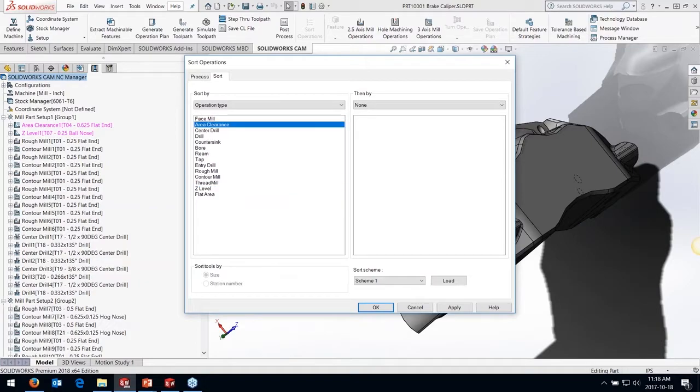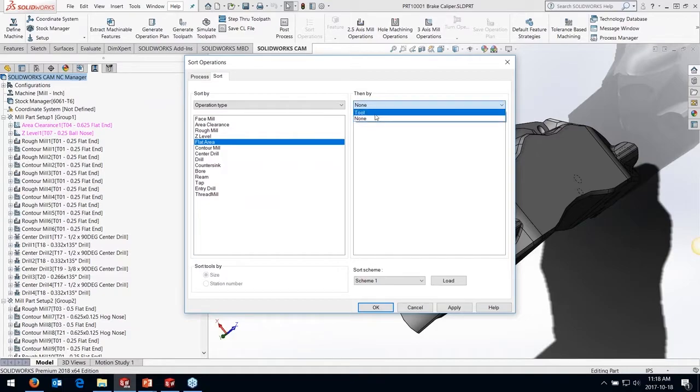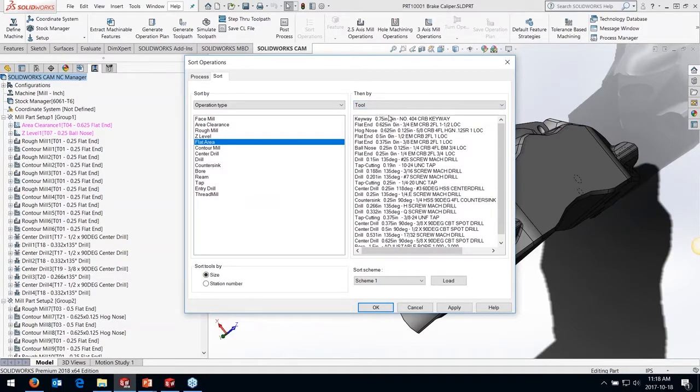Now, if I wanted to add any existing features or any existing geometry to it, it's just a case of finding the machining direction. In this case, my toolpath is coming from this top setup here, going in and telling it some 3-axis features. In our 3-axis strategies, we've got a 3-axis area clearance, which is a rougher, a Z level, which is basically doing like a vertical slice, and a flat areas option.